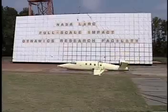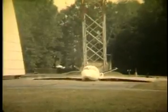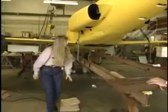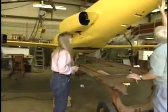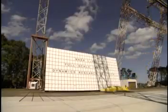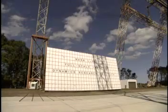Yes, in 1994 we tested a graphite aircraft called the Lear fan. When the original aircraft was released from the gantry, it was extremely rigid and nothing crushed. According to the crash test dummy data we collected, only one of the 6 passengers survived. So we used that data to design a new energy-absorbing, or crushable, subfloor. It would be like putting a bumper under the floor. Then we built and tested small sections of different subfloor designs until we had the best design. A second Lear fan was modified by installing the newly designed subfloor and tested. The results showed that the new subfloor improved the Lear fan's crashworthiness by reducing the forces on the passengers.